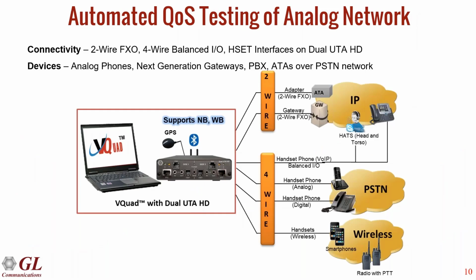Another thing is analog. So analog, we can test on 2-wire analog. So we emulate a phone. That means that we go off hook, we wait for a dial tone, we place a call, wait for a ring back or a busy.